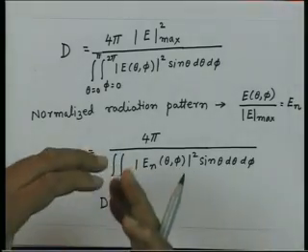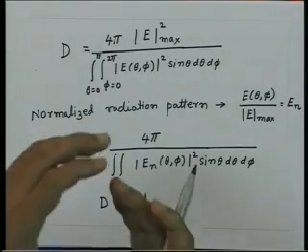And higher the value of directivity, more is the focusing power of the antenna in a given direction. Our interest is to make an extremely high directional antenna, then the directivity should be as high as possible. So, this is what precisely is done when you go to systems like satellite antennas. Those antennas have a directivity which is very high, typically of the order of about 10 to the power 5, 10 to the power 6. So, they have a focusing power which is very high. The power is not wasted in other directions, the power is focused precisely in a given direction.